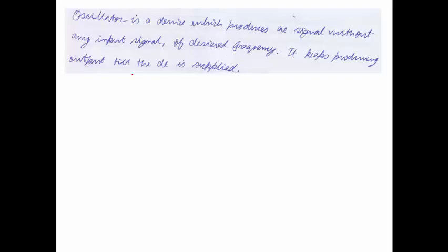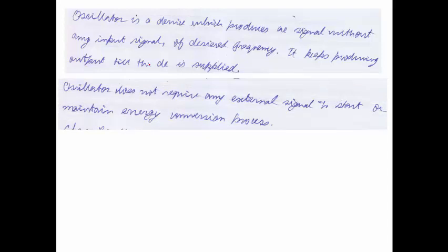Now this is something which is very much amazing. Without any AC input, we are trying to amplify the output, by the concept of feedback, which is called positive feedback. We'll see the functionality in detail in the next tutorial on oscillators, where we will discuss Barkhausen's criteria and the way it is applied to an oscillator. There we'll make it very clear how we actually generate it. So it keeps producing output as long as the DC is supplied. As long as we have a DC input at the oscillator, we are able to get the output in terms of AC.